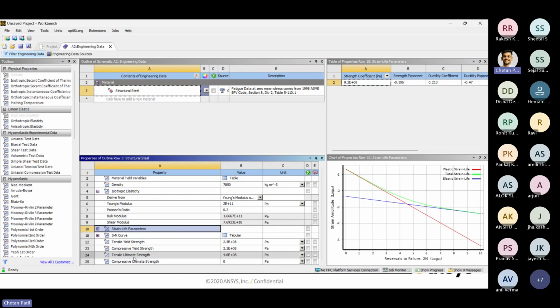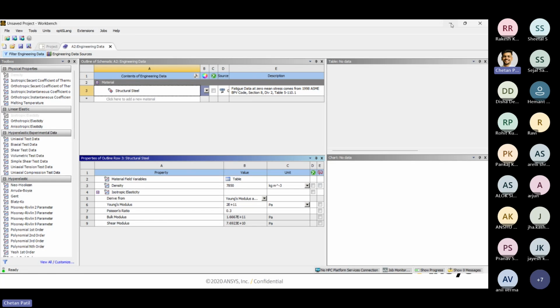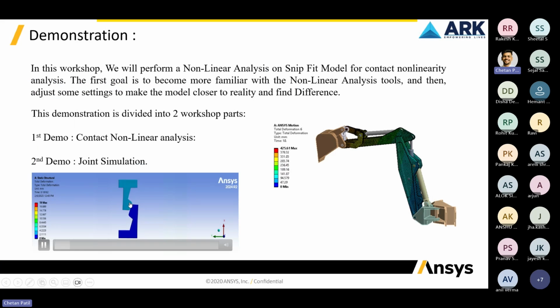I'll be using only the linear elastic properties itself, because as you can see, both the bodies are undergoing some deformations and then coming back to their original position. But the upper body is undergoing a very high amount of displacement. To recognize and consider that higher deformation, we will be turning on the large deflection option over here.